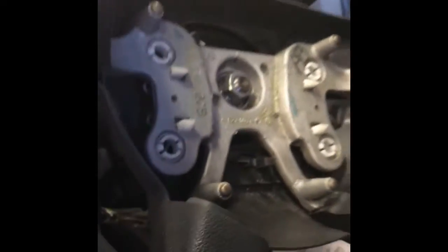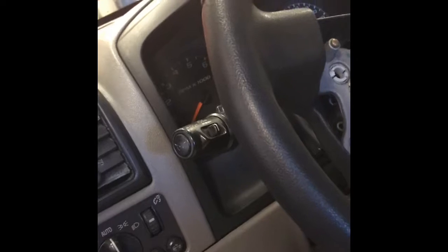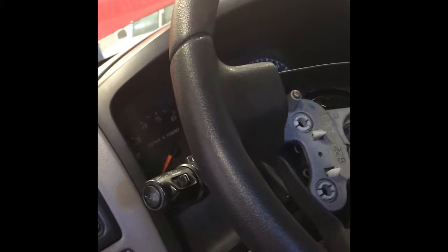Alright, this vehicle here has a rack and pinion type steering system that runs across the vehicle and is connected via tie rod ends at both sides. Here we have the steering wheel and steering column, which runs down through the firewall down to the steering system. The steering column transmits the driver's steering effort from the steering wheel down to the steering box. The steering box converts the rotary motion of the steering wheel to linear motion needed to pivot the wheels.